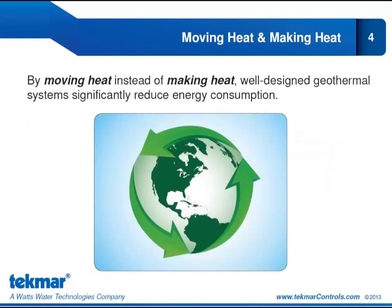By moving heat instead of making heat, geothermal systems are able to significantly reduce energy consumption. In fact, Natural Resources Canada states that heat pump systems can reduce heating and cooling costs by up to 65%. Now that's for a geothermal heat pump. Heat pumps still use electricity, but they're able to operate at much higher efficiencies than traditional heating equipment. And we'll take a look at those higher efficiencies later in this presentation. The reason they are able to offer these high efficiencies is because we are transporting heat rather than creating heat like a furnace does when it burns natural gas or propane.